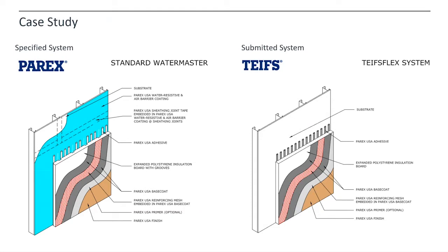Yes, the drainage pattern behind the EPS or XPS. Okay, can you elaborate on that? That's basically the secondary layer for draining the water if there's any condensation in the system. There's a drainage pattern behind that insulation board that allows water to drain from the joints. Okay, what else do you notice that's similar in both images?